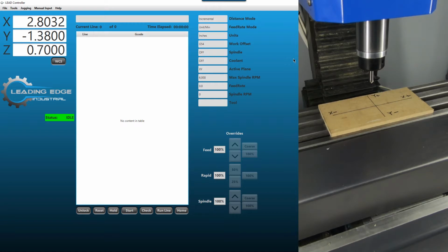So we're going to jump up, and on this one here, we're actually going to set these two corners as G56 and G57 offsets to continue working on our G54 through 59 offsets. We won't go as high as the 58 and 59 because you'll get the gist of it after this, but you'll be able to see where we are on this. So what we want to do is use the jog menu, and we're going to jog over to the upper left corner of the sheet.